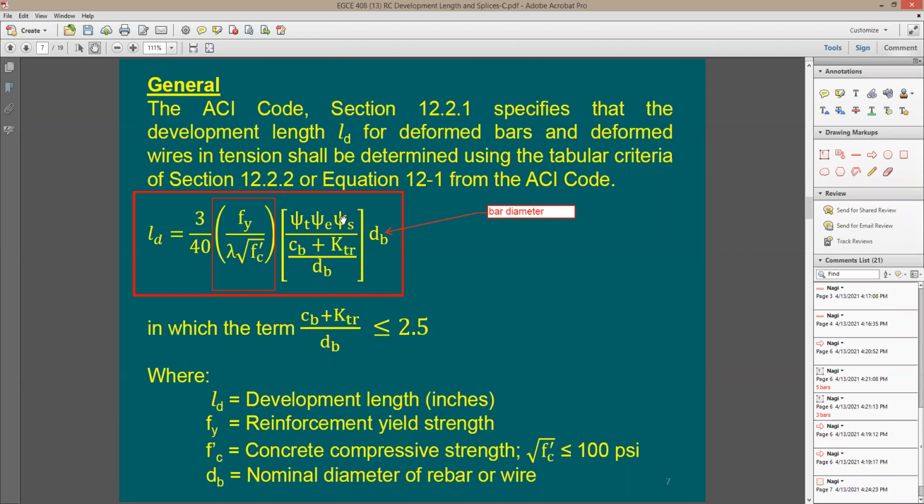Thank you, Zuli. So it's going to be 0.6 square inches, meaning that each one of these number 7 rebars is equivalent in cross-section area to 2 number 5 rebars. Am I correct? Roughly 0.6 versus 0.62, they're almost the same. But how about the surface area?